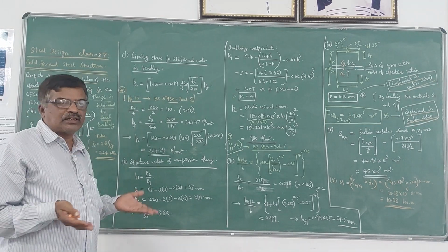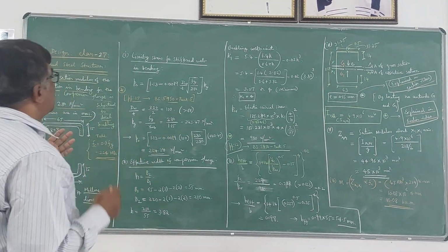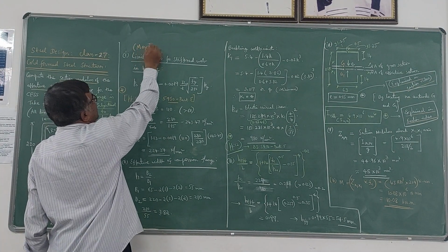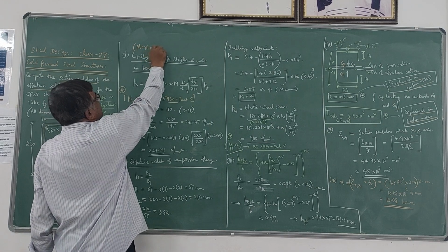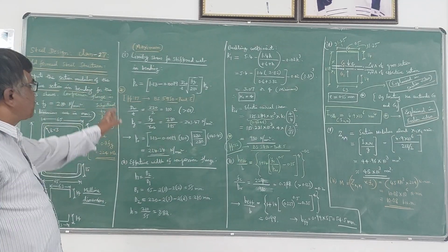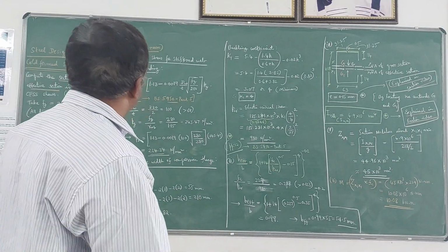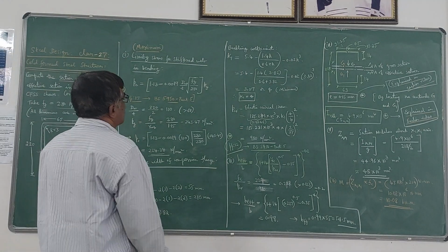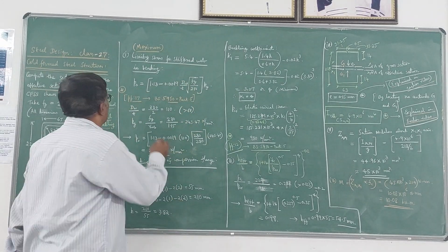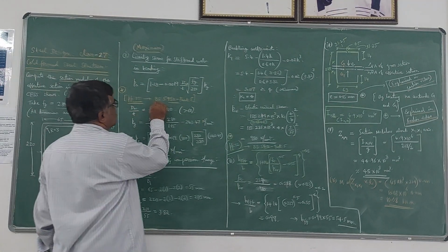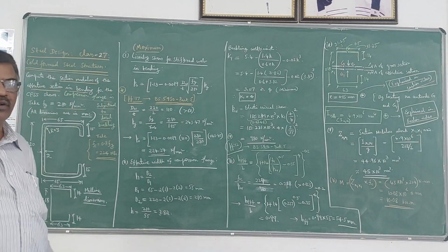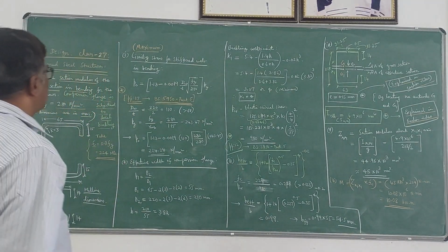Now the procedure is like this. First we have to calculate the limiting stress or the maximum stress for the stiffened web in bending. In the last video also I have explained about this. It is given by this formula: P0 is equal to (1.13 minus 0.0019 dw by t) root of (Fy by 280) into Py. This is there on page 17 of the BS code. The BS code is also allowed in the examination. BS, British Standard Code 5950-5. So refer to page number 17.